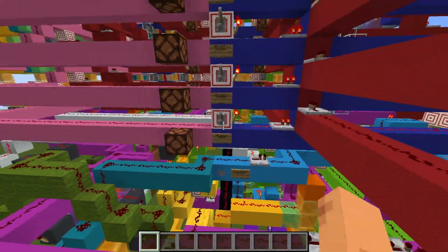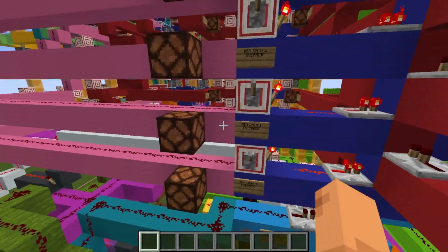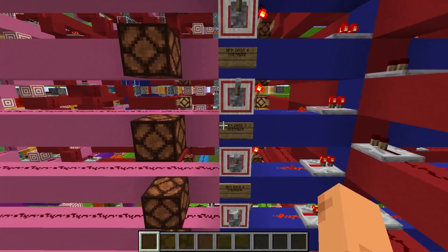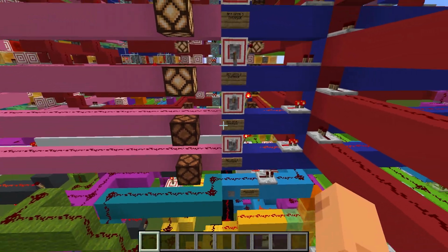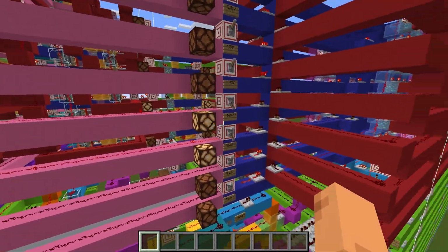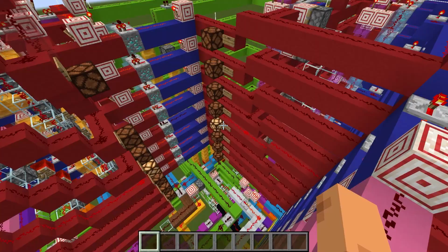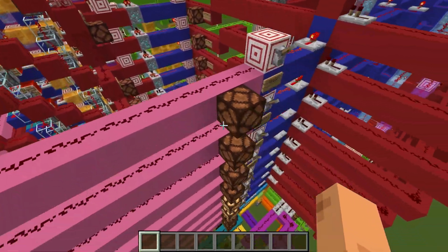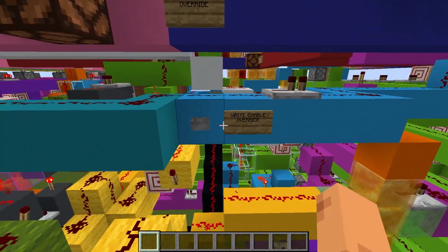So if, say, we want to program byte 0 to be 12 instead of 8, we'll enable bits 2 and 3. We have that programmed here, but that does not change the memory cell. But we have this button here, the write enable override.